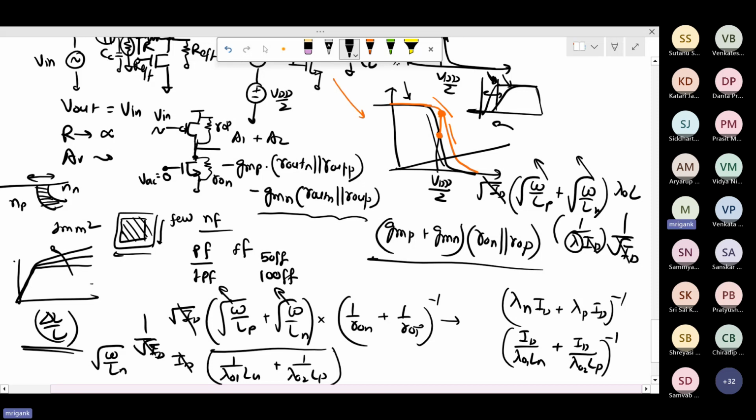So this part you can check, what is happening. Again, the exact derivation, taking all the terms of NMOS and PMOS, will lead to a more extensive derivation. But the trend is that if you want bigger gain, you can try to increase the length. And from the W point of view, because of the gm, if you derive it exactly, the residue W will be coming in the numerator.